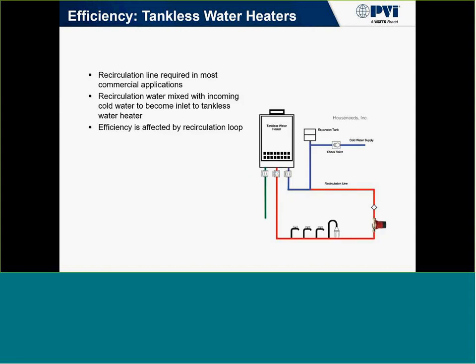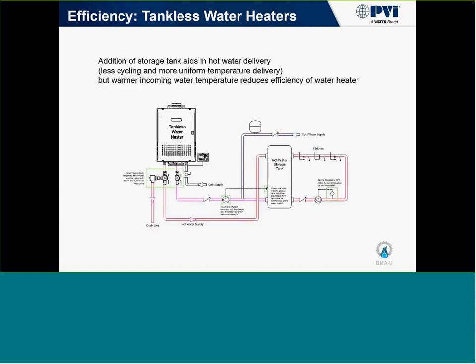So in most of our commercial type designs, we're going to be using a recirc pump. I believe that's a standard now where you can't even have dead legs anywhere, so we have to be able to bring that water back. And what's going to happen is we're basically preheating our water that we're throwing into that tankless water heater. So looking at it, even if you couple with a storage tank or the rest of the system, you're preheating your water that you're feeding that tankless water heater. So we're no longer giving it 70 degrees. It's at a much higher temperature. So especially with a hot water storage tank, if we're close to that, your incoming water temperature is going to be drastically higher.